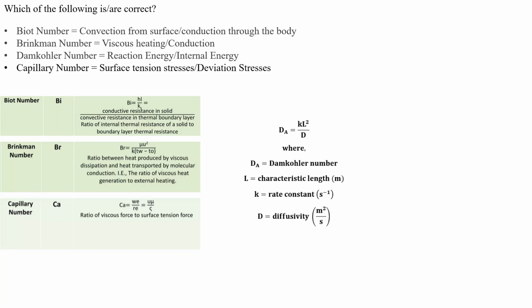So to explain this, you can imagine a solid sphere which has been dipped into a tank of water. It has a high temperature. The sphere has high temperature and it is continuously losing heat to the surrounding water. So what's going to happen is the heat from the center of the sphere will first have to conduct and travel through the radius of the entire sphere, and then it will leave the surface of the sphere to the water. So there the convection process will occur, and inside the body you will have the conduction.